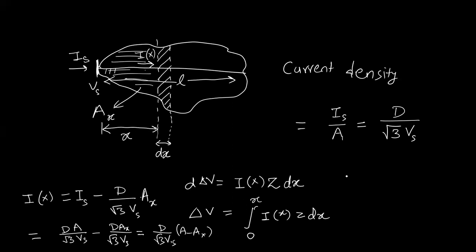Once we get the current, similarly we can calculate the power loss also. The power loss in the incremental section is basically 3 I squared R, where R is ohm per kilometer. If you multiply that by the feeder section length dx, that gives the incremental loss in that incremental area. And if we integrate that from length 0 to L, that gives the total power loss. So if you plug in the values of I of x in the voltage drop equation and power loss equation, we get generalized expressions for voltage drop and power loss.